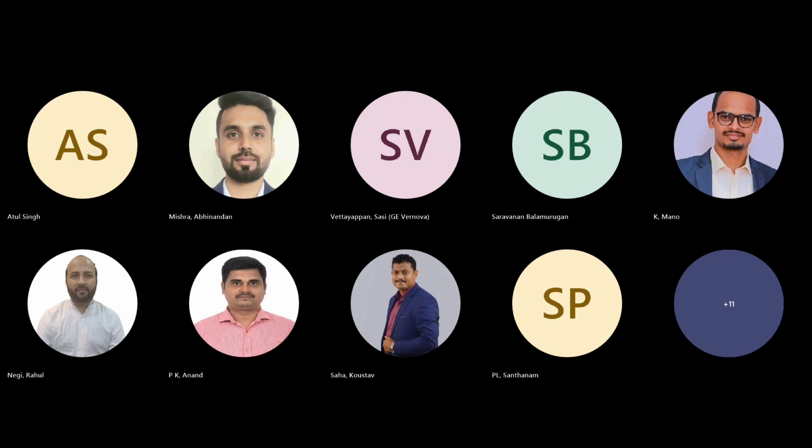And if we go by statistics, what CIGRE published in around 2016, the last survey that they carried out, around 37% of the failures had happened within the first 5 years, and then around 29% of failures happened after the end of life period, meaning around 25 to 30 years or even more than 30 years of age. In the period between 5 to 20 years, only 14 to 17% failures were reported worldwide.